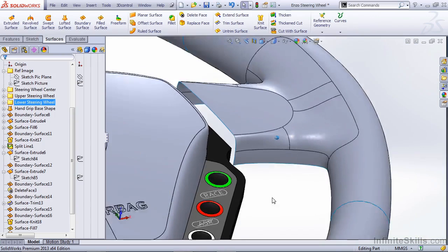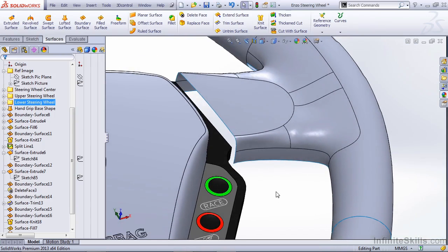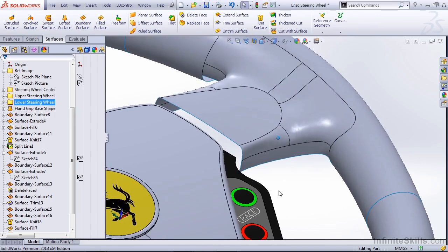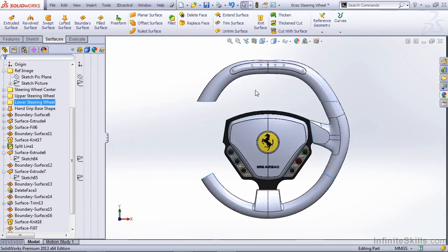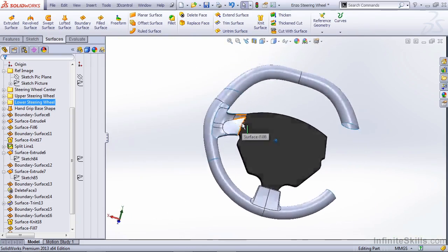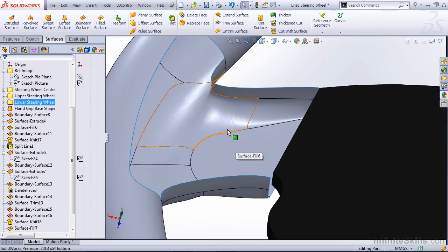Because we're dealing with SolidWorks, a parametric modeling program, we don't have complete control over these surfaces as if it were a complete free surfacing program. So it's important that you don't try to over-define your surfaces. In this case, because we have very little information about the surfaces we're creating, it actually gave us a little bit of extra freedom. The process we're going to follow for the bottom is the same, with the exception of needing to blend everything together with a turn signal area.